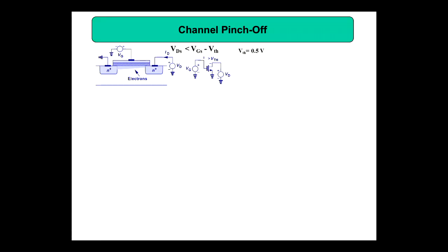It means if you are operating below 500 millivolt, then your MOS transistor is off. Now it is above 0.5 volt, so your VTH is 0.5 volt. Then, as I said, I will take another condition, VDS equal to VGS minus VTH. Then I also will take another condition, VDS greater than VGS minus VTH.